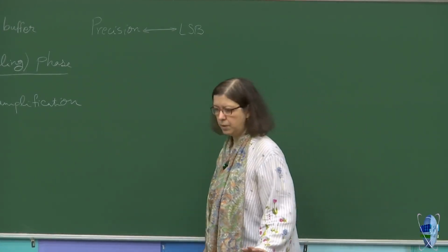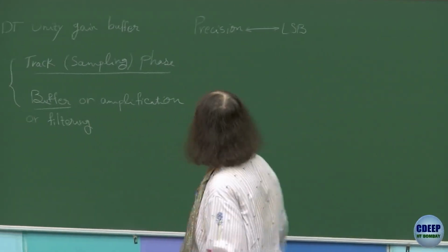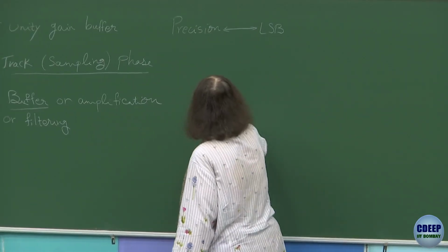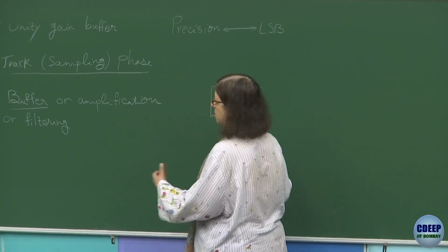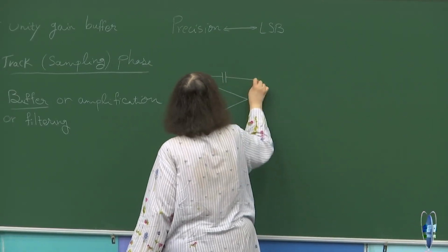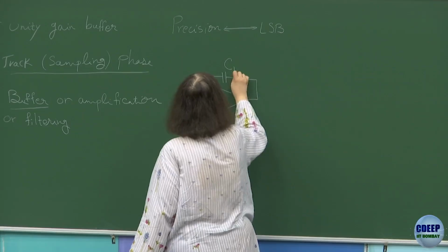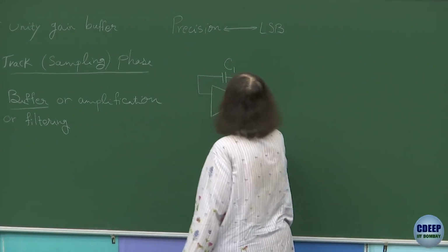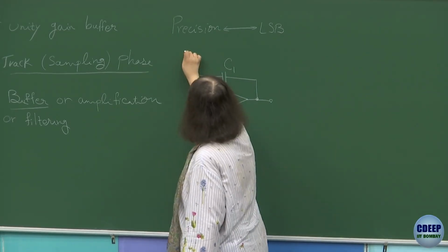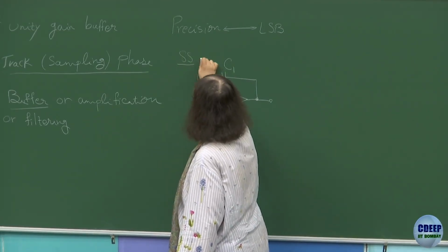Okay, so one thing which was very important last time was to consider a simple passive track and hold. The only difference was we were keeping the sampled input around an op-amp, and this is small signal analysis.